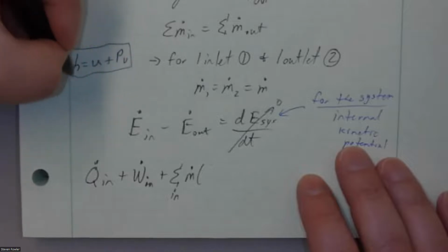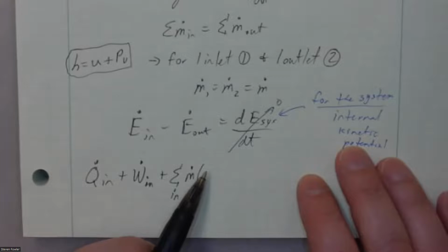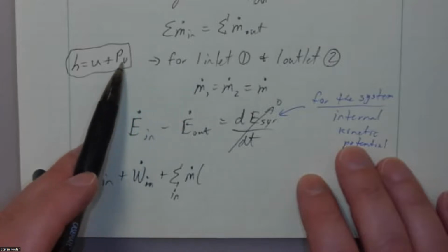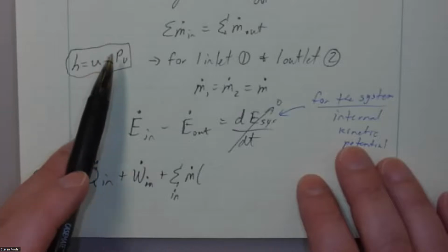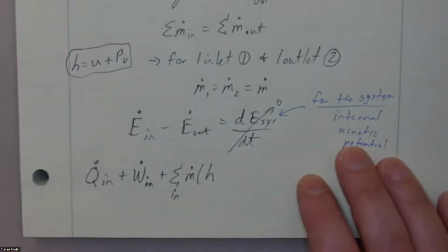So, kind of a side note here. Why is it an h value? Why not just have u down here? Well, because it's not stationary. If it's stationary, it would only have a u value, but because it's flowing, something has to cause it to flow, and that's the push of the fluid upstream. In most cases, it's just the pressure of the fluid upstream. What causes that pressure? I don't know. It could be a pump, it could be a piston, it could be something. Something's causing the fluid upstream to push the fluid downstream out of its way. So the sum of that u and the push of the fluid upstream simply results in an h value.